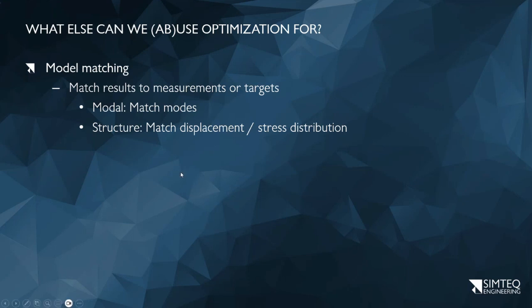I still have design variables I need to change, thickness and stuff, but how do I do that? In that case, the simplest approach, and I'll explain the more complete one in a moment, is to simply say my cost function is some coefficient, which for the moment isn't important, but will become important in a moment, times the difference between what the mode should be and what it is, and we square that number. If you don't square it, then the problem is my optimization will run in the wrong direction. We'll try and minimize a mode instead of minimize the difference between modes.